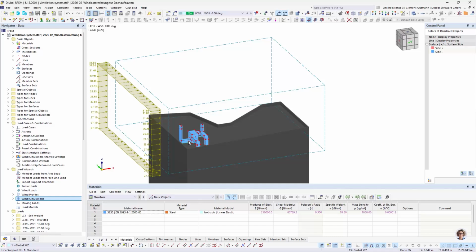And to minimize that error, it is important that the calculation mesh, so the volumetric mesh, has a smaller density or equal density than the shrink wrapping mesh. So if the shrink wrapping is finer than the volumetric mesh, the error increases and gets too high, or let's say it's not sufficiently accurate anymore.